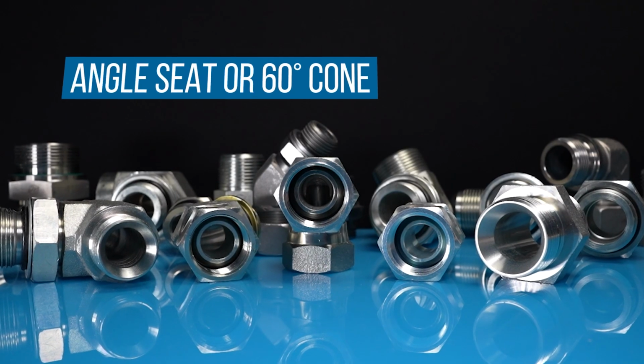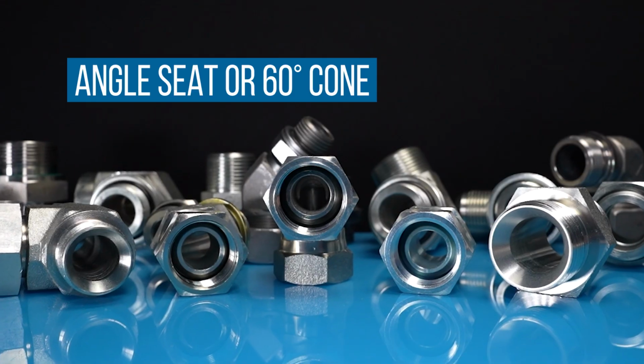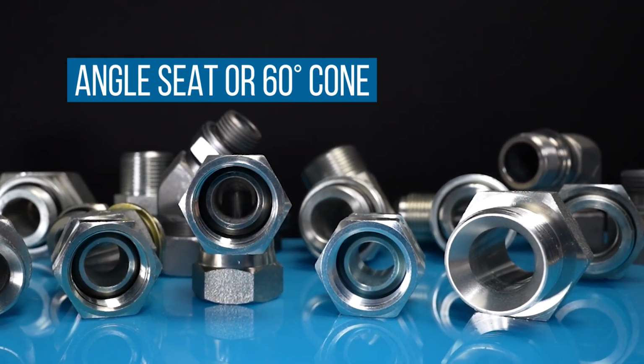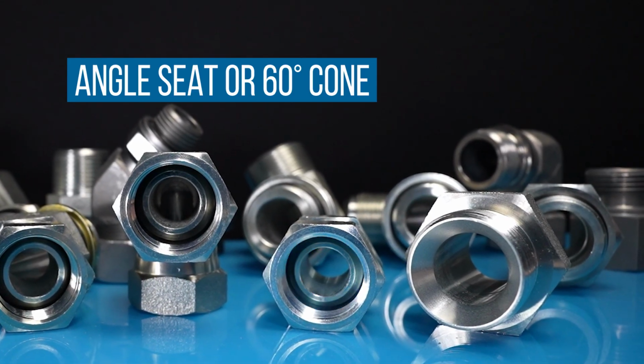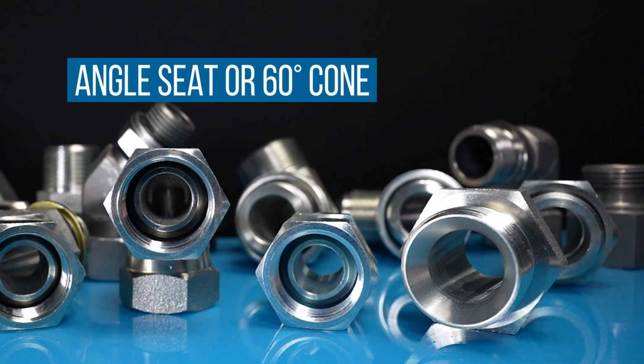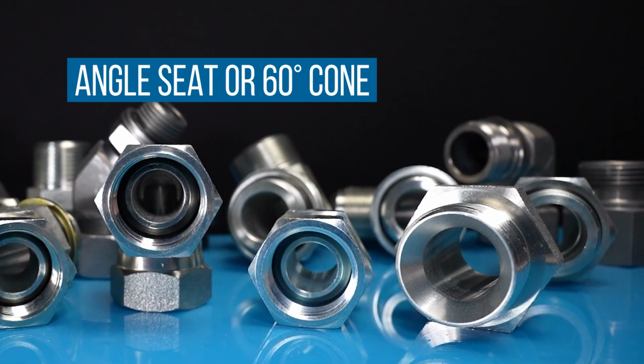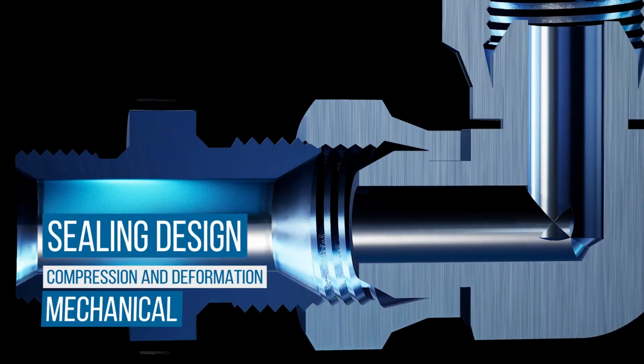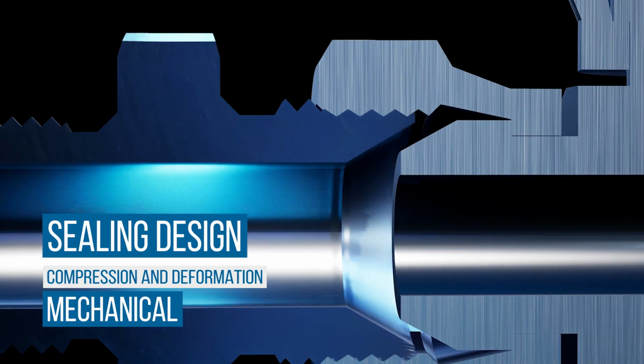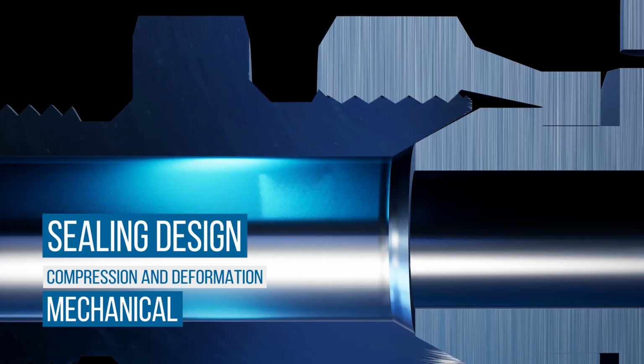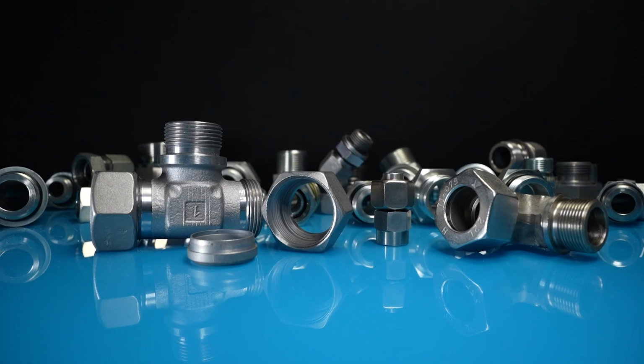The angle seat, or 60-degree cone, is another type of sealing design whereby the opposing connections utilize a coned female end and a chamfered male end combined with a swivel nut to create the seal. This metal-to-metal connection relies on the compression and deformation created between the two mating angles as the swivel nut is tightened.